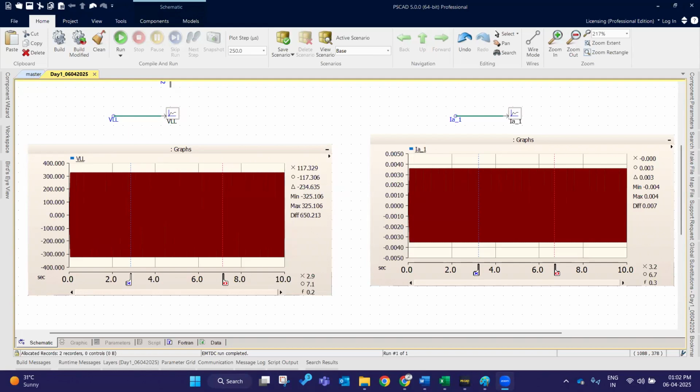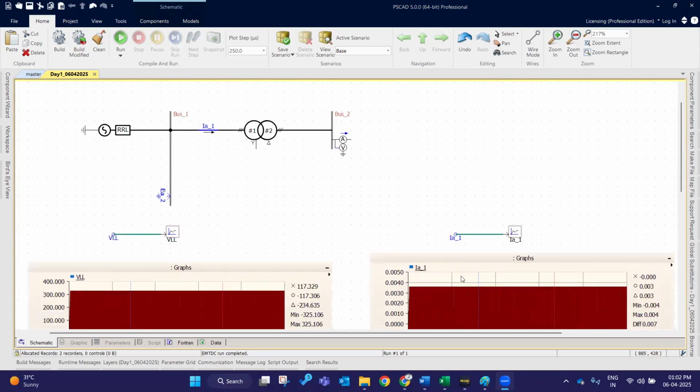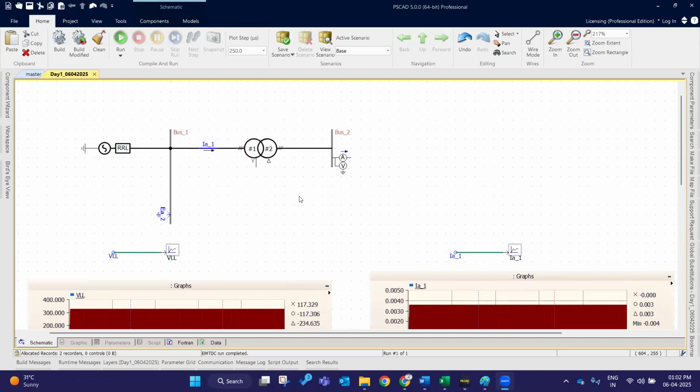Yes. Thanks. So for seeing the inrush current, that is what we are observing now. On the transformer's HV side, I am including this IA1. The current we are measuring now is actually the inrush current, right? Before that, we would include a breaker and suddenly close that breaker, so that the action acts like energizing the transformer from new. But here, it is directly connected to the source. The current we are measuring at the transformer's incoming feeder is the inrush.